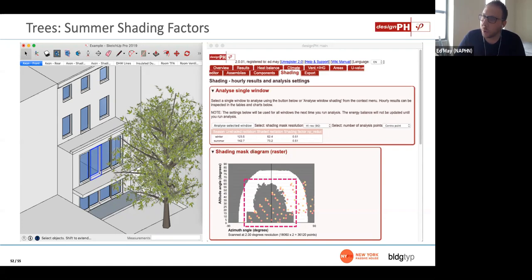Then Ryan asks, where are you getting site geometry and how accurate does it need to be? Does it calculate reflected radiation? Good question. Where we get the site, there are two things. Site topography, so hills and such, we're bringing in from the geolocation. As I indicated earlier, when you geolocate through SketchUp using the import tool, it automatically brings in the topography data.